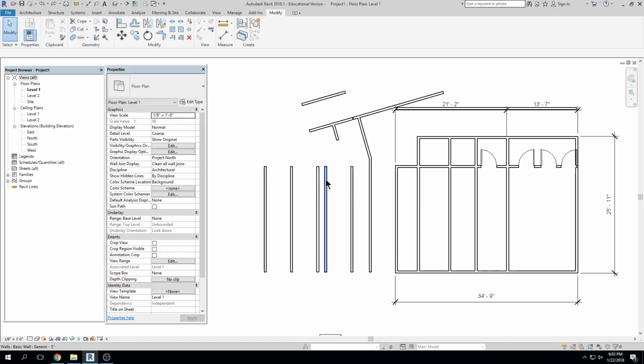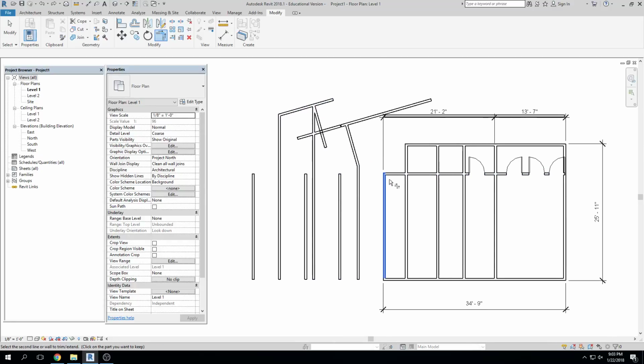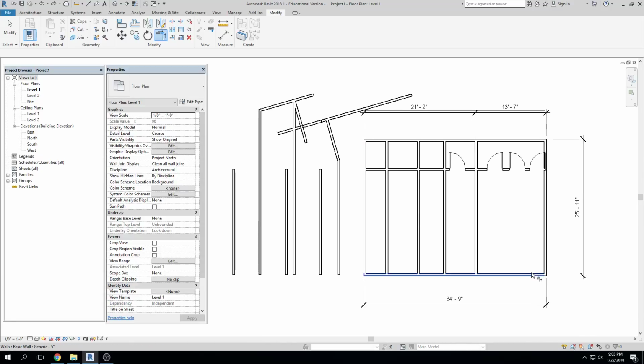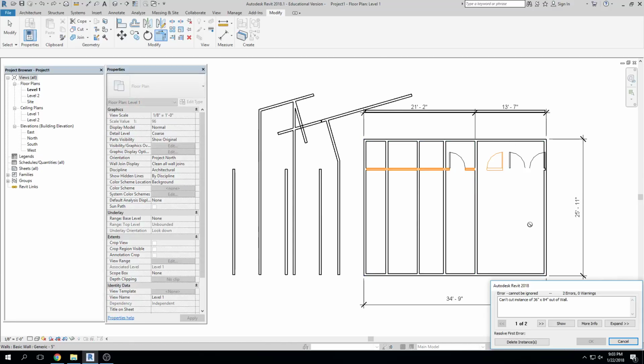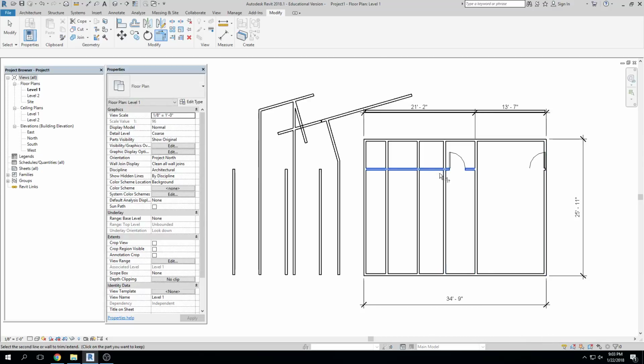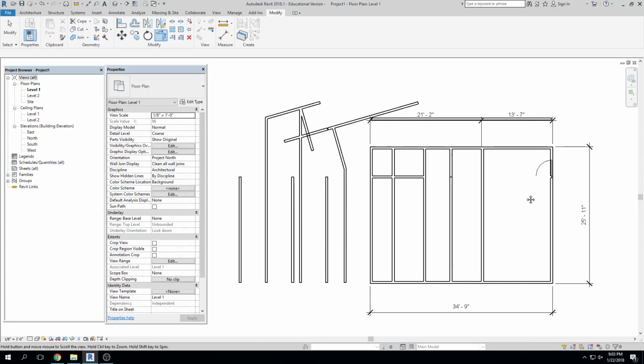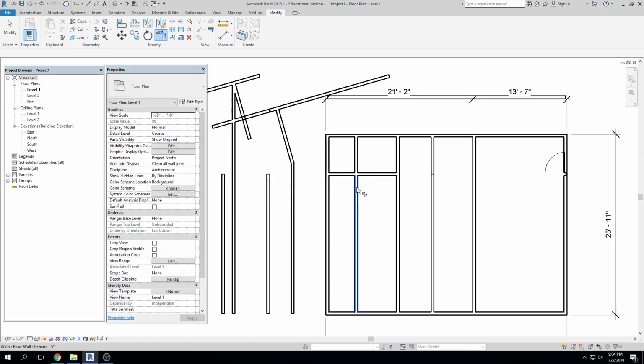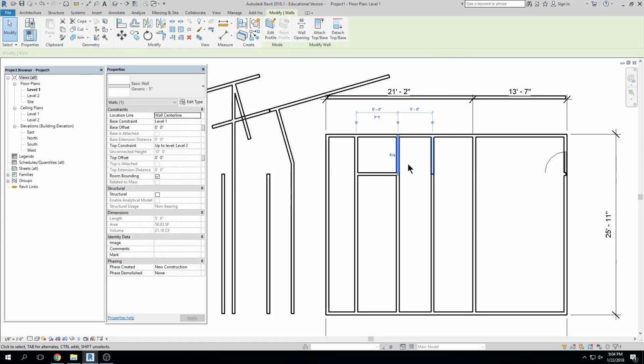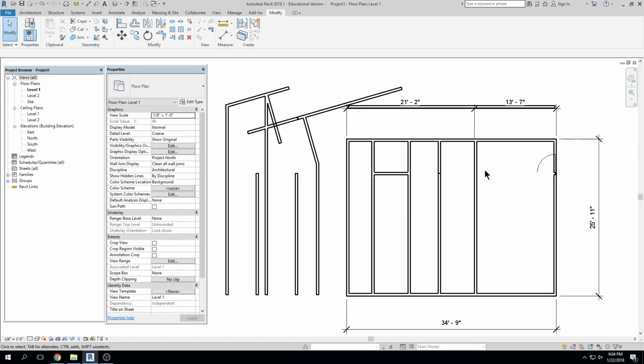Let's try and trim, TR, click, click, and we'll just do some nice little trims here. Trim, TR, click, click, right? But this is really how you're going to start trimming. Click, click. I'm going to delete. Trim, trim, delete, trim, trim, and join. I'm doing all these errors everywhere, but you guys get the idea, right? It's just taking these objects, trim, trim. Ooh, does anybody know why that one's not trimming? It's a separate piece, right? So this piece is already trimmed to that piece. That is just an extra piece above it. So that's why that wasn't trimming.